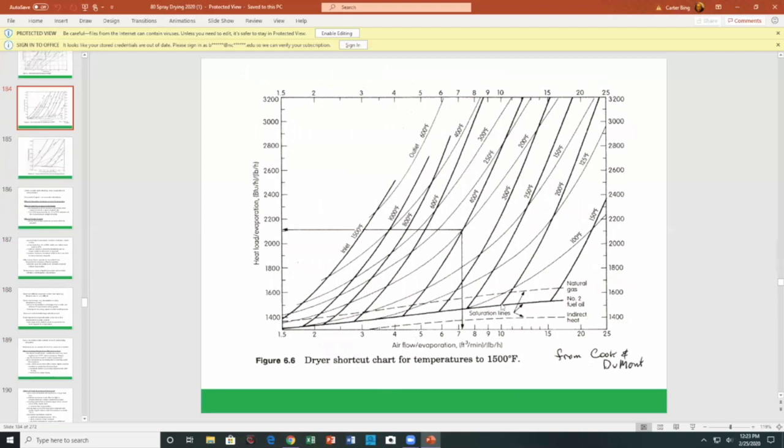Higher the delta T. So what does higher the delta T mean? If I'm going from, say, this point to this point to this point to this point, what happens, right? The difference here is 50, the difference here is 75. So I have a higher delta T and I have a higher heat load. And then my line's going through here, I go from 50 to 75 to 100. So I'm following that line up. It gives me a trend. I have higher delta Ts going this way.